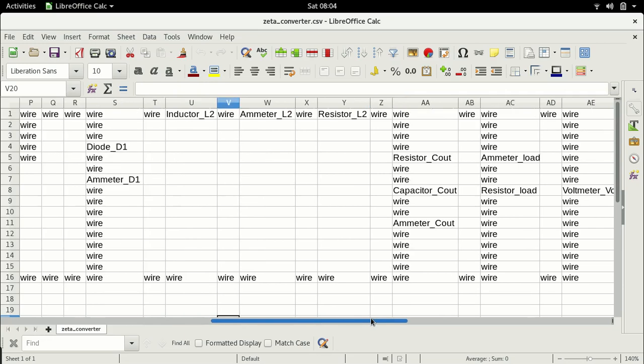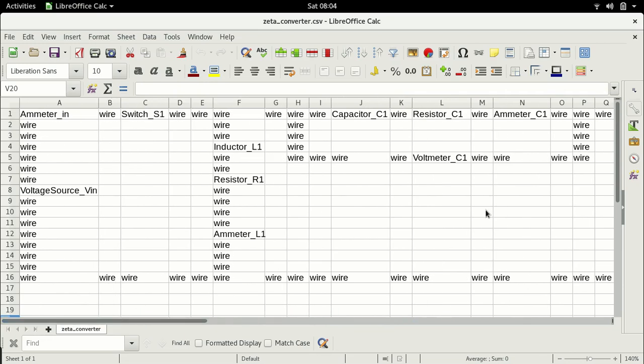Now, if you were to apply Kirchhoff's voltage law, that also adds up. For example, if you look at when the switch is turned on, this is a loop. So, as per Kirchhoff's voltage law, the sum of all the voltages in this loop will be 0, which means the input voltage plus the inductor voltage will be 0, which is why the inductor voltage is equal and opposite to this input voltage.